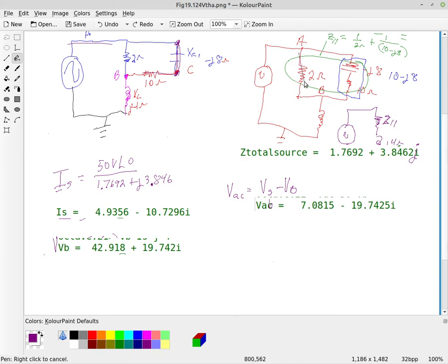And then we used Kirchhoff's voltage law to find this voltage, because we took the supply voltage minus VB, and that left us with the voltage VAB. So now I'm going to use Ohm's law one more time. All we're doing is applying Ohm's law and Kirchhoff's voltage law, and if you need to, maybe Kirchhoff's current law, and we can figure out what's happening in this circuit.